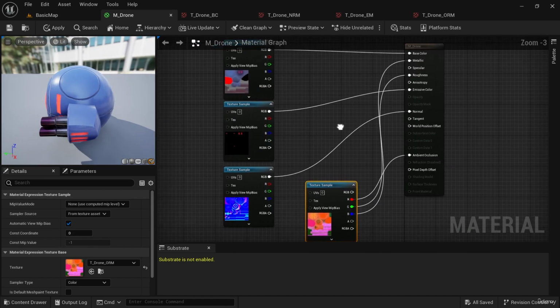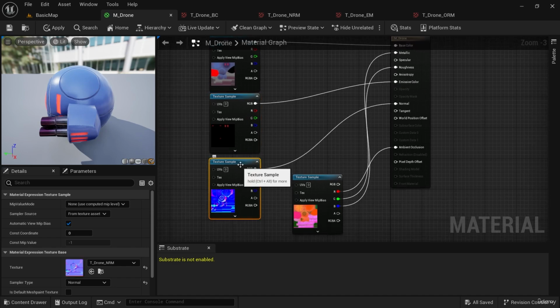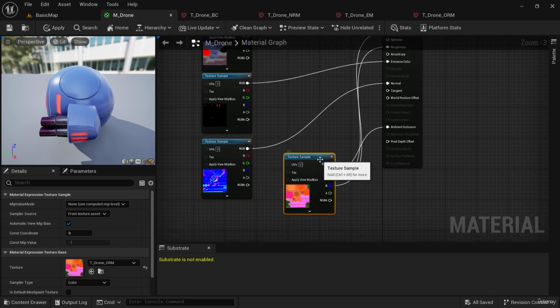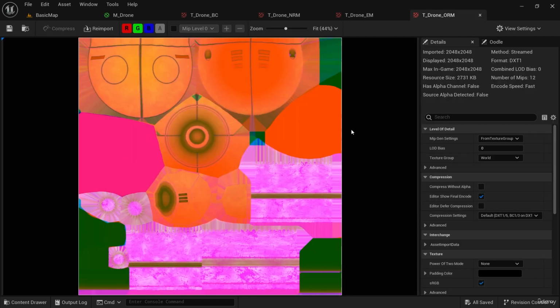And this is often the form that you'll see textures in. You'll have a base color texture, an emissive if there are any glowing parts on the mesh. We'll generally always have a normal map. And then ambient occlusion, roughness, and metallic are often packed into one single texture, because those grayscale values can be packed into the red, green, and blue channels of a single texture. So that's just an optimization technique.